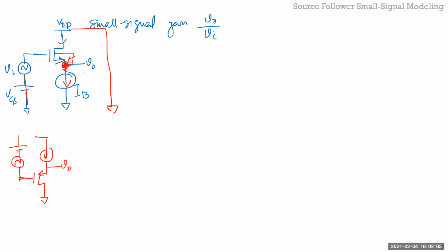No, okay. So the first thing is, obviously, you should ask me which region of operation it is, right? That's not guaranteed because the VDS could be in linear region. So when you're designing these amplifiers or source follower, you want to make sure that this is in saturation. That's the assumption to begin with, because the small signal analysis we did was for saturation, right? If you're in linear, then obviously it's not going to be a source follower. So the assumption is it is in saturation region.